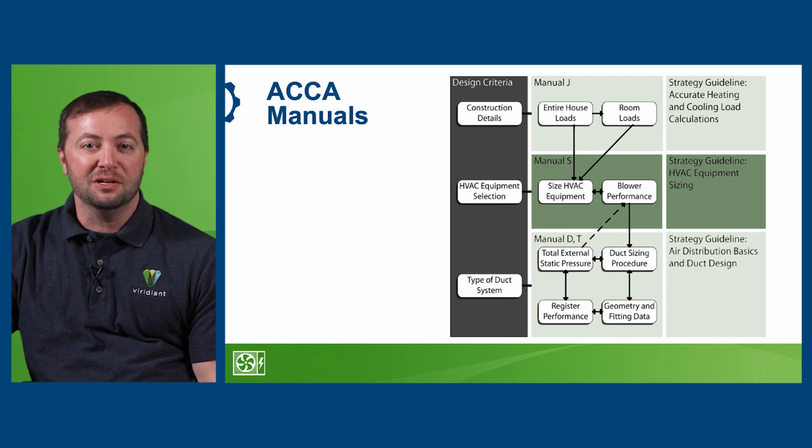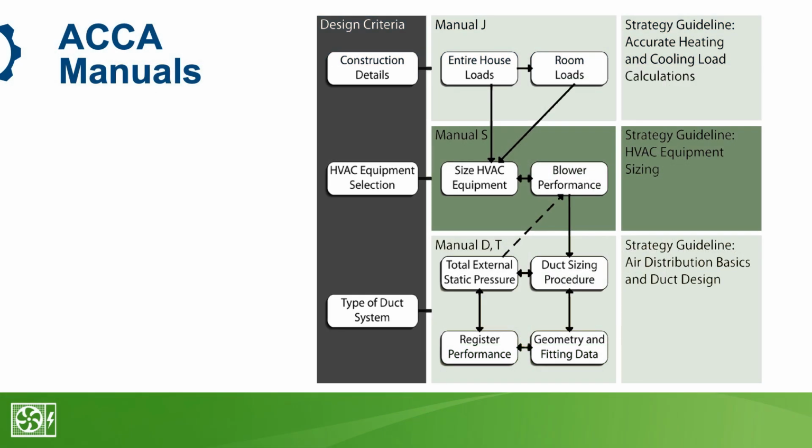Use the software that's available. Using the software also definitely applies for existing homes. It's not just for new homes. Just duplicating the capacity of an existing system in an existing home may give you the right answer or it may not. It's highly likely that when the existing system was installed, it wasn't sized using the Manual J, and there have likely been improvements or changes to the home itself, such as air sealing, insulation, windows, other energy efficiency measures that may have occurred since then as well, which would impact the size equipment that that home needs.